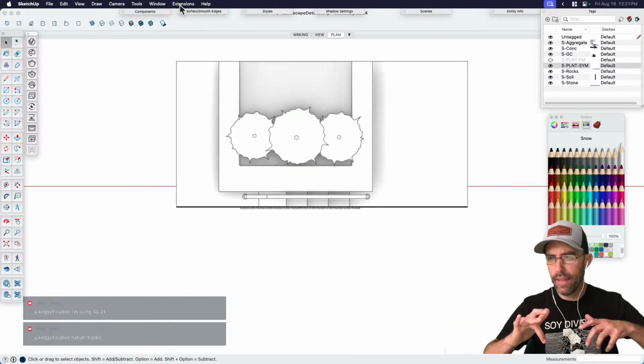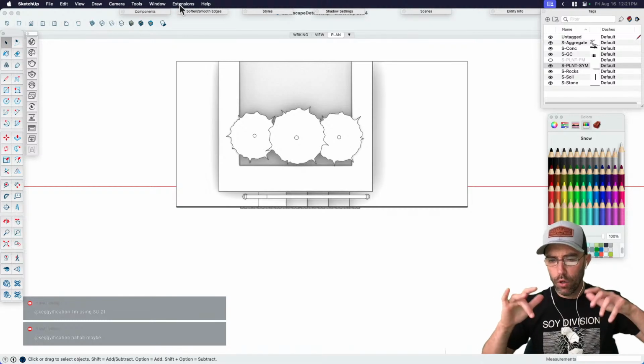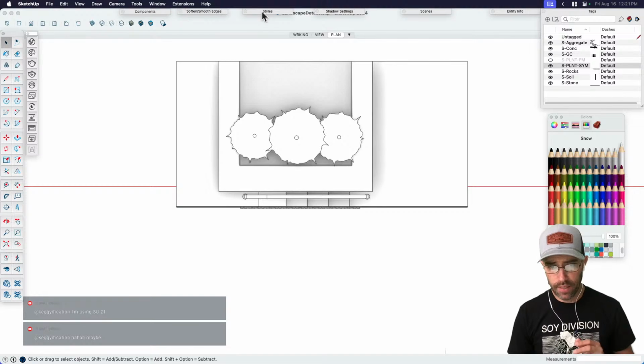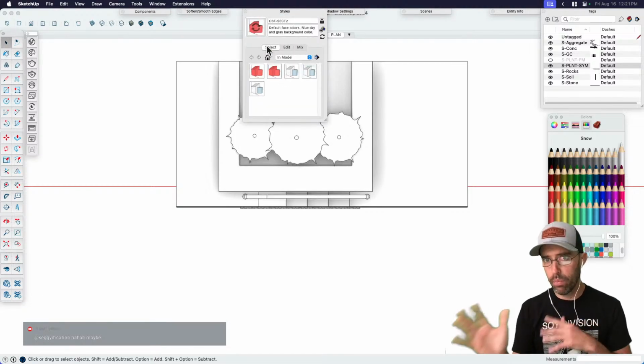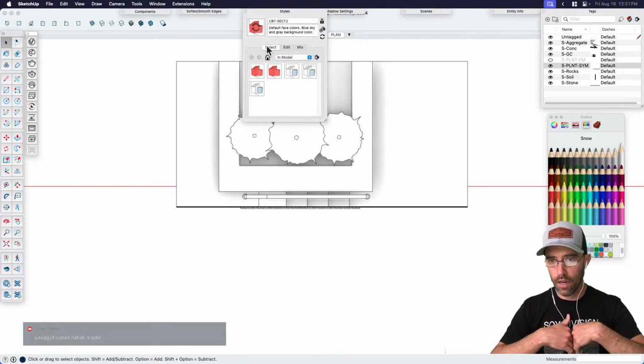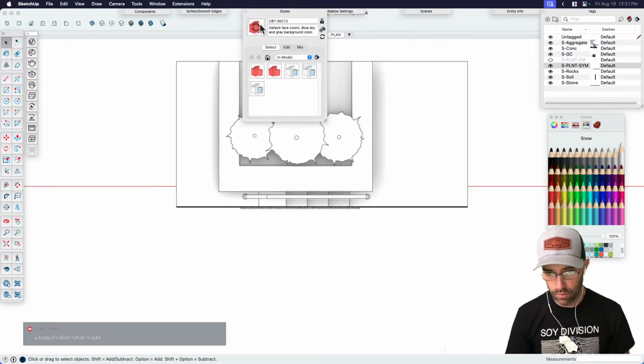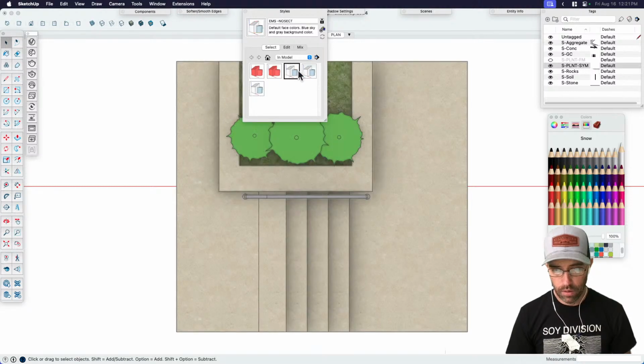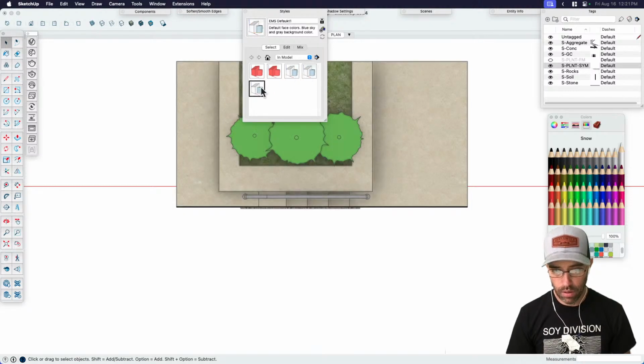And I don't need to apply them. You don't need to apply them to a scene. The only problem is you want to be careful not to purge, because if you've got a bunch of styles here and you don't have them applied to scenes, and then if you purge unused, it's going to get rid of them. So in this case, what I'm going to do is just: no section, section. No section, section. I've got a duplicate, so I'm going to delete that one.